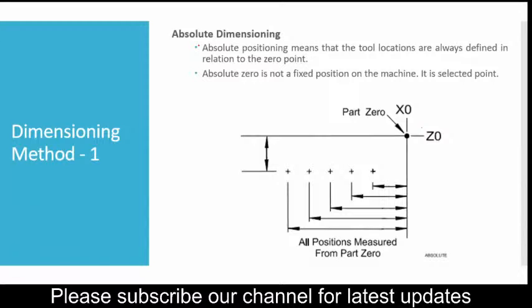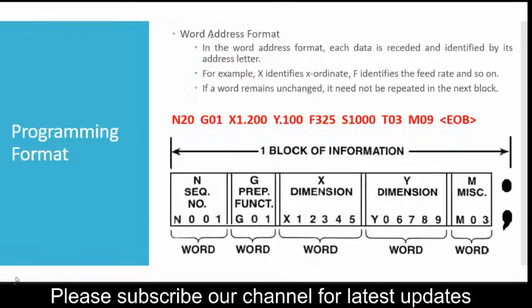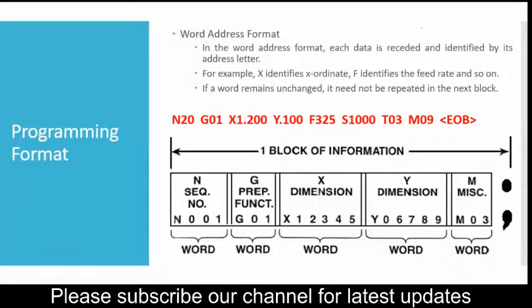For that, if you are using 3 tools in a particular program, then you have to take the offset of each and every tool, which means that you have to take offset 3 times in the beginning of the programming. Okay, is that clear, Kaushik?